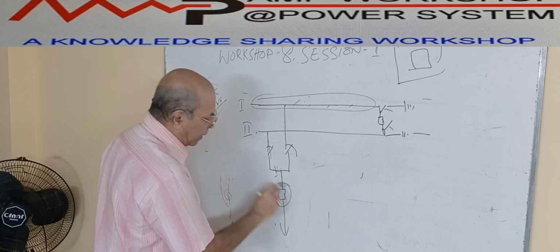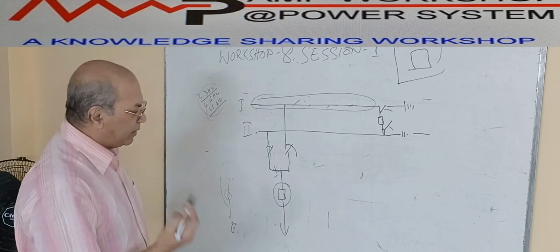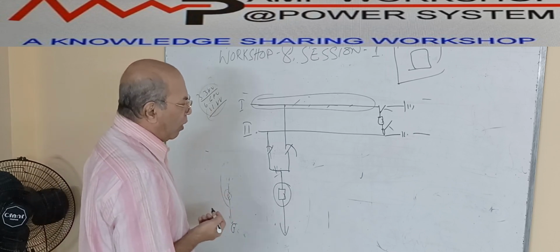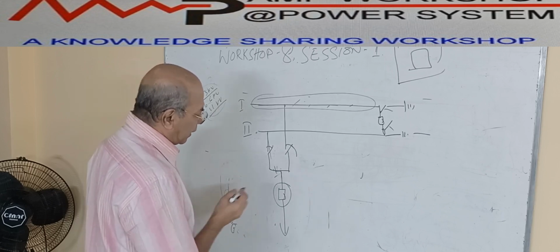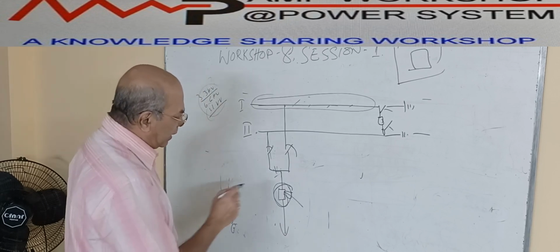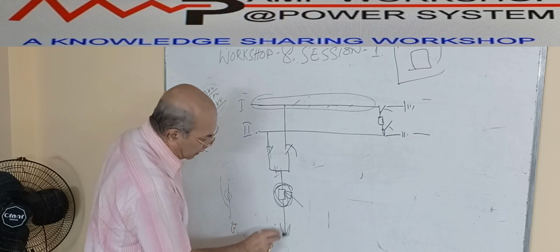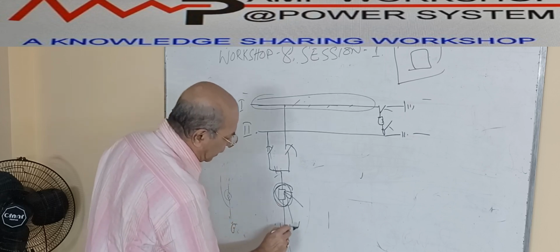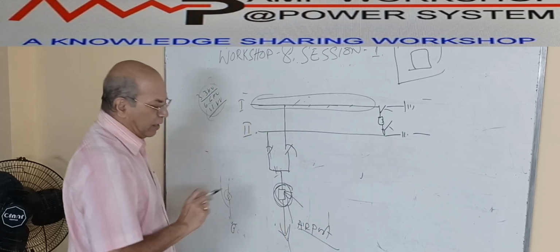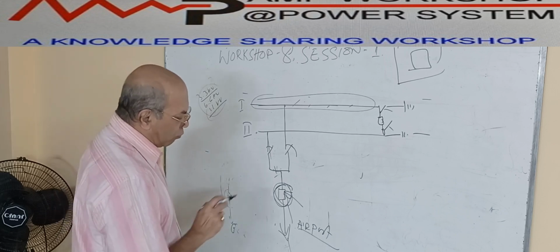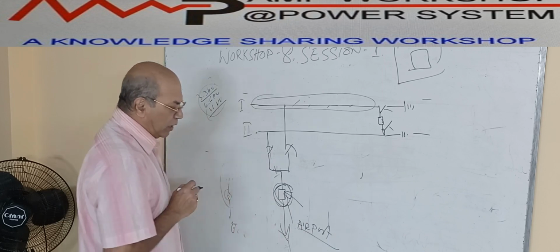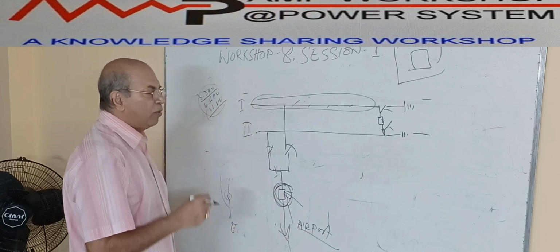But it is a single breaker. Now sometimes, in an emergency power plant or an emergency utility substation where power supply is very critical, suppose this breaker has a problem. Till this breaker is repaired, you will not get power from here. Suppose this feeder is going to the airport. In that case, the power supply is very critical, so we cannot put off this supply even for 1 minute. So what will we do here? Instead of a single breaker, we will go for a dual arrangement.